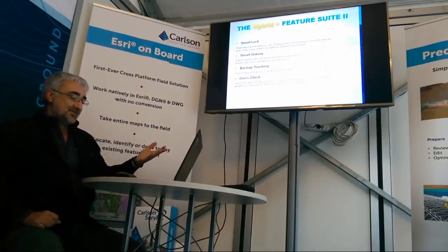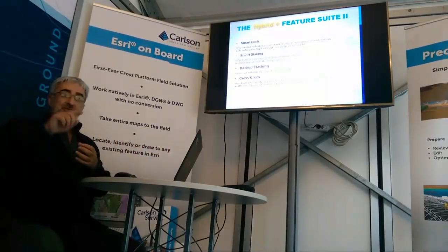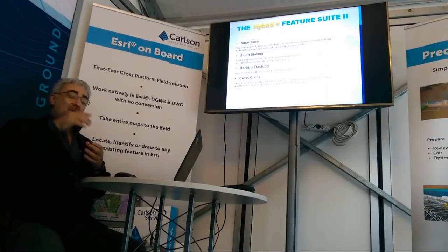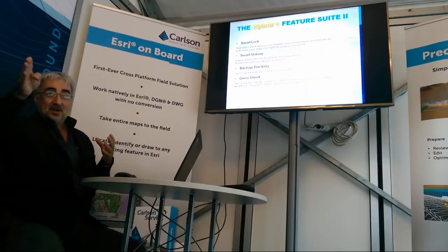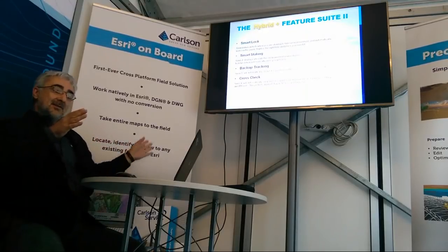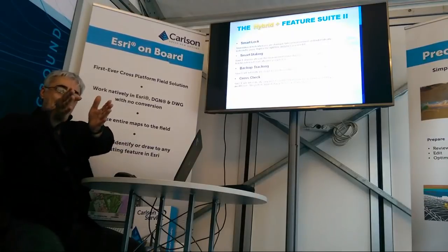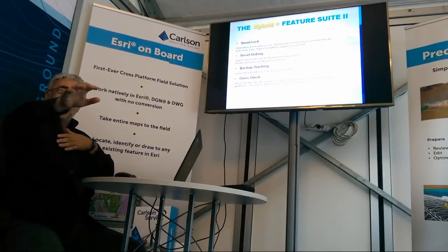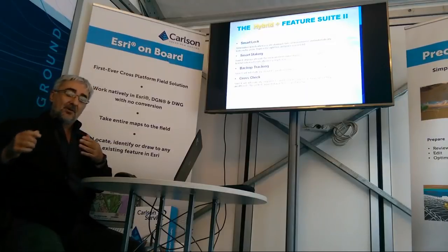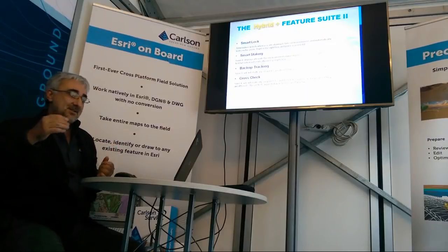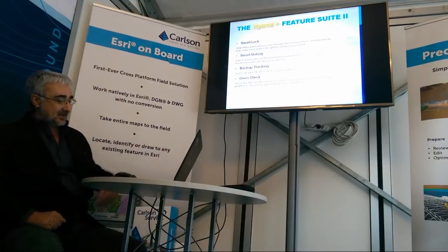The Smart Lock works a bit different because it knows your target, knows you're going to a point. So what it does is wait for you, looking to the point, and when you get in the field of view of the distance meter, because we know more or less the angle and the distance, you know where we are, that is the time to start searching, so we can lock the prism the soonest possible. That is the Smart Lock, Smart Staking.